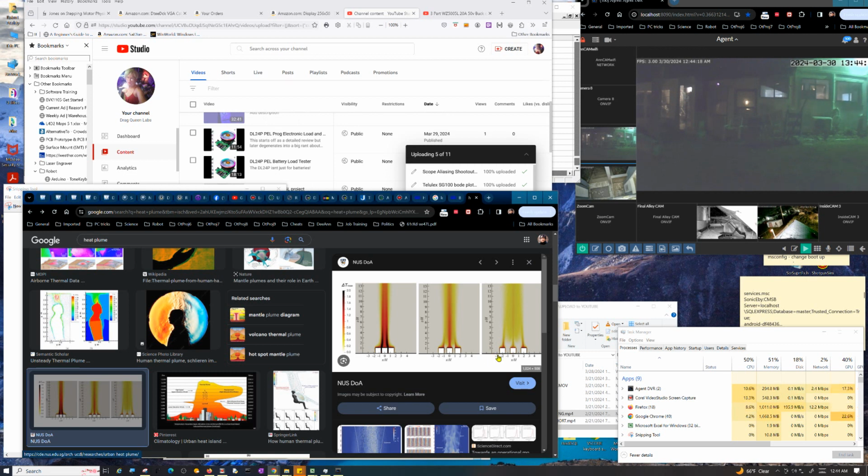So again, you really want to measure the temperature of any component laterally or underneath it if it's in free air. So you might have some power resistors mounted, just soldered to some terminal blocks or something like that, to keep them away from your circuit board and other components. It's not a bad practice if you're really dissipating a lot of power. But in that case, you should measure the temperature maybe half an inch or so underneath the component, because that's the air that's most directly going to be drawn into the component to cool it. That's ambient air, all right?